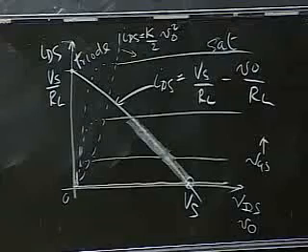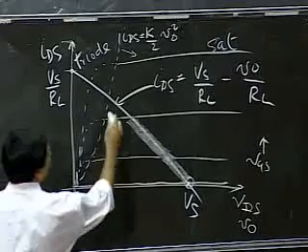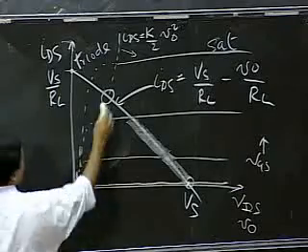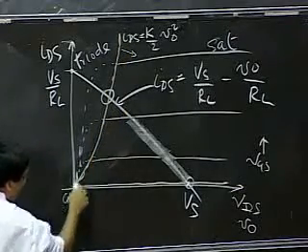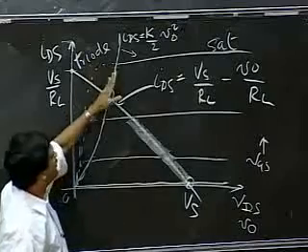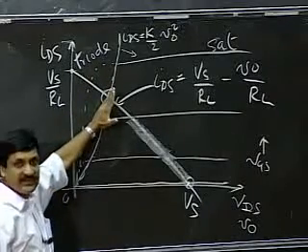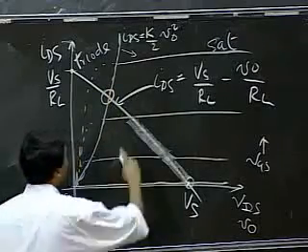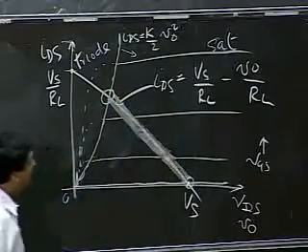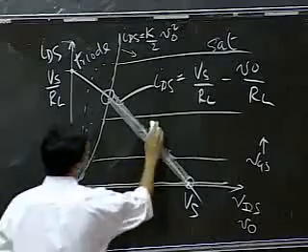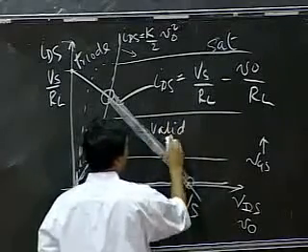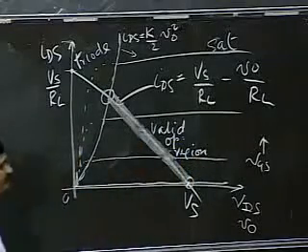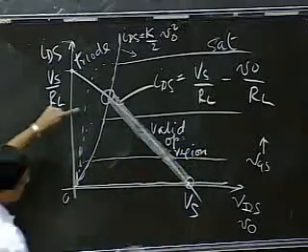And that other point is given by this one. So notice that this is the curve that bounds. On the left-hand side of this, the MOSFET is no longer in saturation. It's on the right-hand side, and so therefore, this is the valid operating region. Here to here.